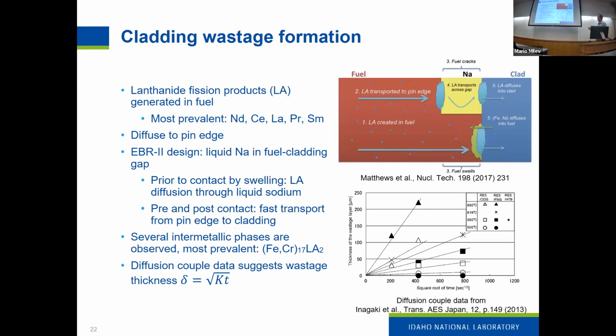EBR2 fuel had liquid sodium in between the fuel and the cladding, so before contact, it would diffuse through the liquid sodium. After contact, it just directly goes across the fuel. But in any case, that step we don't think is that important because the transport is fast either way. Transport through liquid sodium is fast. Direct contact is also fast. So that's probably not the limiting step.